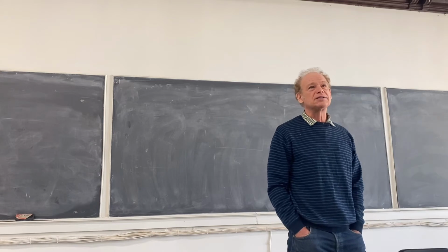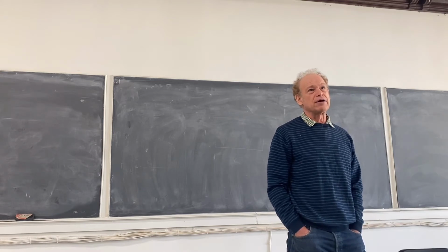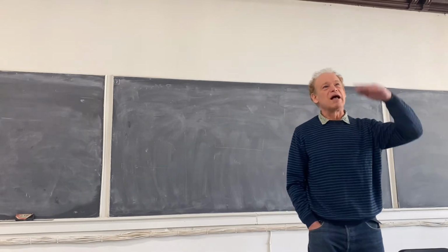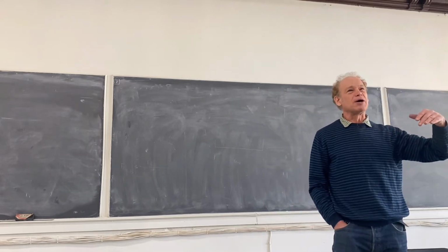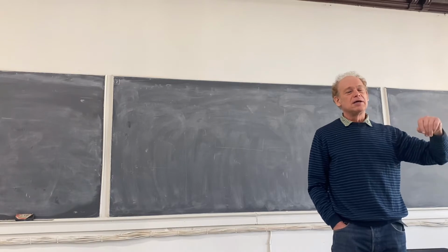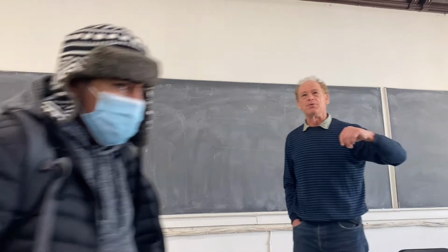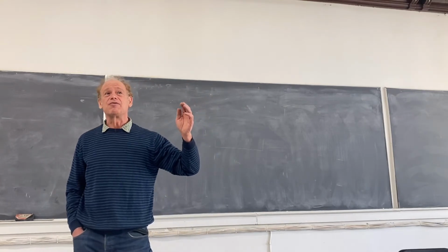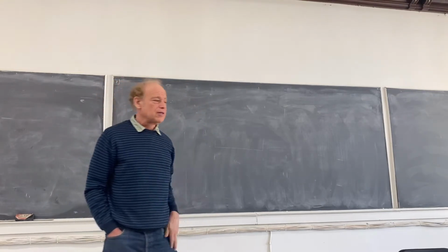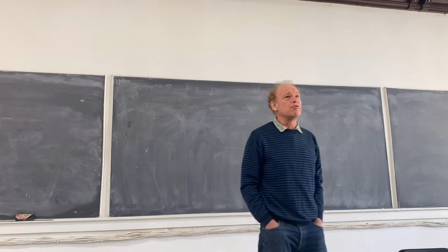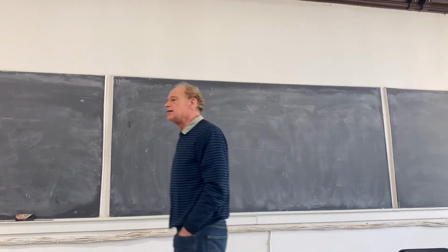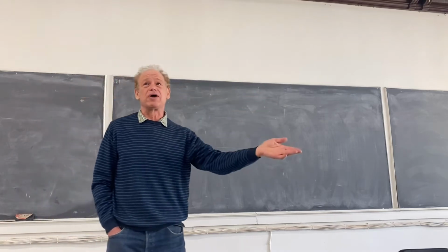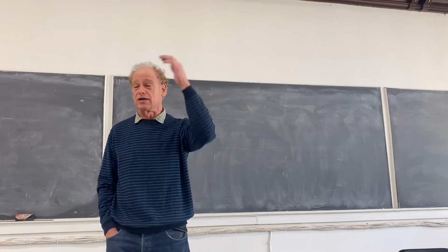Most of the class could not write energy balances on these 2 systems correctly. I'm not talking about solving the problem. I'm talking about writing an energy balance. There were at least 5 people who just wrote mass balances. Didn't even write energy balances. There were also a number of people that didn't realize that since you have 2 reactors, you need a separate balance for the first reactor and a separate balance for the second reactor.